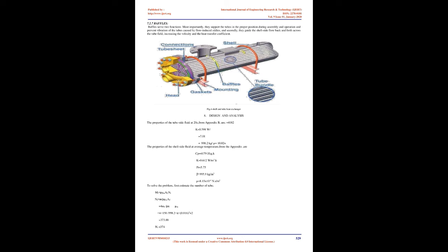Authors concluded that for an overall consideration of a heat exchanger with maldistribution, the parabolic model is satisfactory. The parameter P-par depends on both NTUs of the heat exchanger, which makes the model difficult to handle. The advantage of the parabolic model is that only one parameter is needed. The hyperbolic model is superior to the parabolic model because it predicts the axial temperature profiles correctly, especially temperature jumps and positive slopes. Ming Suan and Wilfried Roetzel applied the dispersion model to the description of the effects of shell and tube side flow maldistribution.